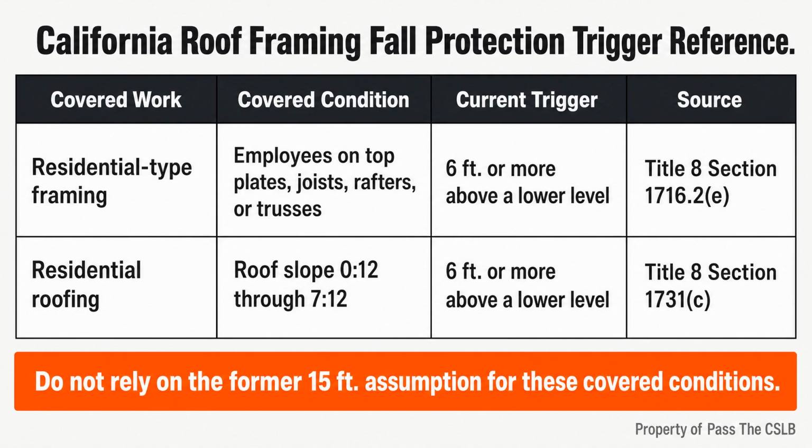I want you to leave with one clean mental picture. Divide the attic triangle into thirds. In the bottom third, the rafter tie, or a qualifying parallel ceiling joist, resists outward wall spread. Think 2x4 minimum and 24 inches on center maximum for a wood rafter tie. In the upper third, the collar tie resists wind uplift separation at the ridge. Think 1x4 minimum and 4 feet on center maximum, with an allowed ridge strap alternative.